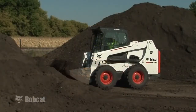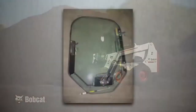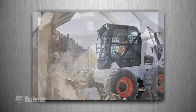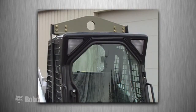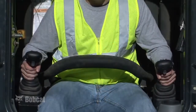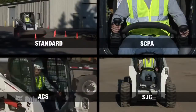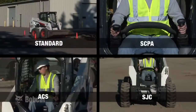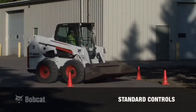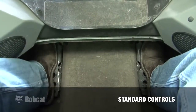Your particular job application could require additional accessories or equipment, such as a special applications kit to restrict materials from entering the cab, single-point lifts, or a fire extinguisher. The controls used to operate machine functions may vary depending on the model and control system on the machine. Loaders equipped with standard controls provide steering levers to control drive and steering functions, and foot pedals to operate lift and tilt functions.